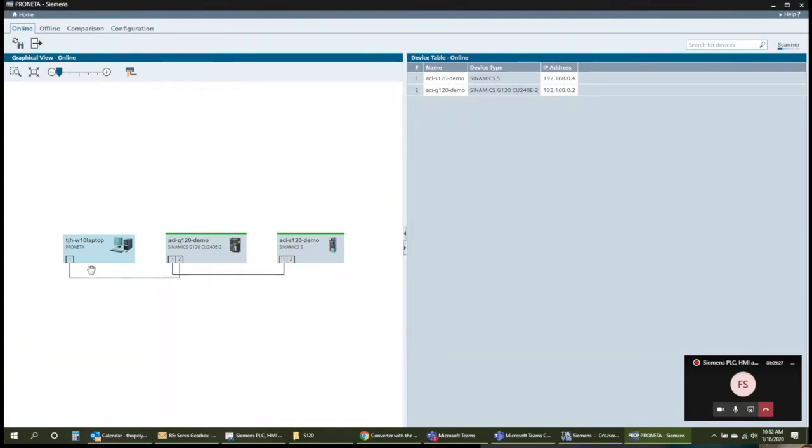And it's really nice. Like I said, if you're using Profinet IRT, it requires a certain topology, and not everyone knows that. And if they go to replace a device and they swap those 2 plugs into the 2-port switch the wrong way around, it's never going to work, right?